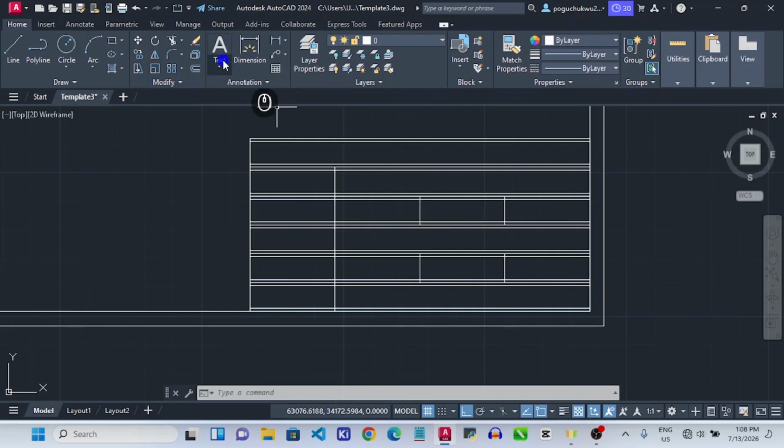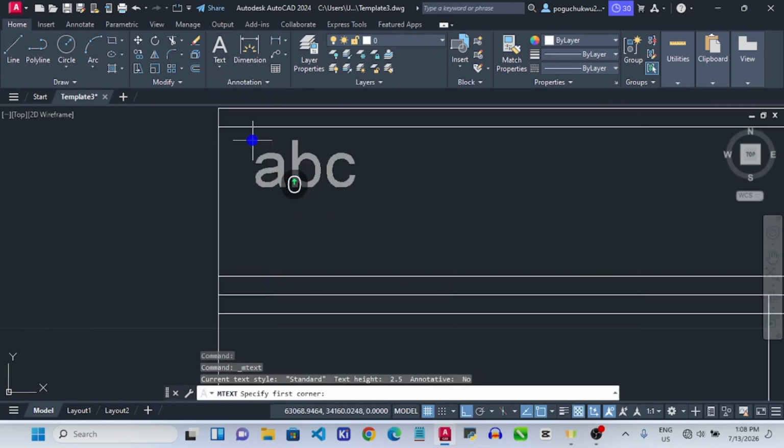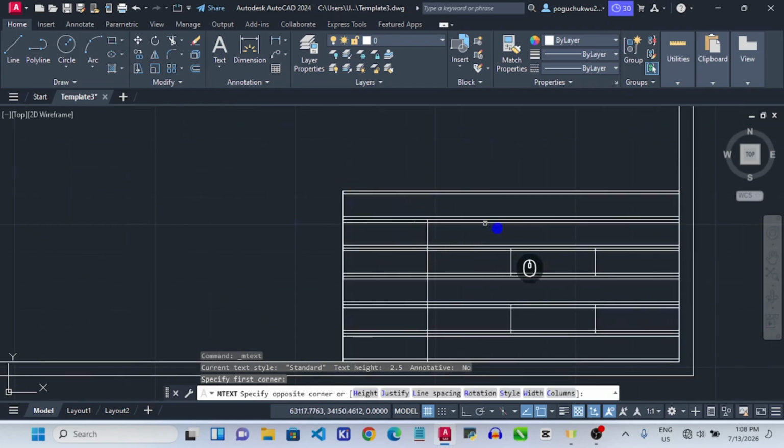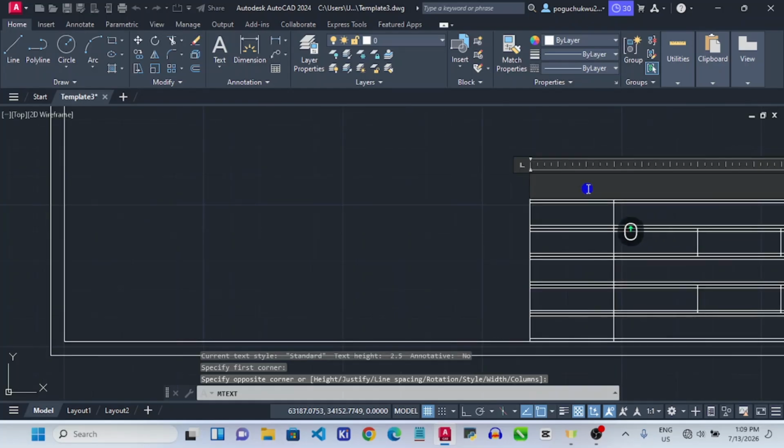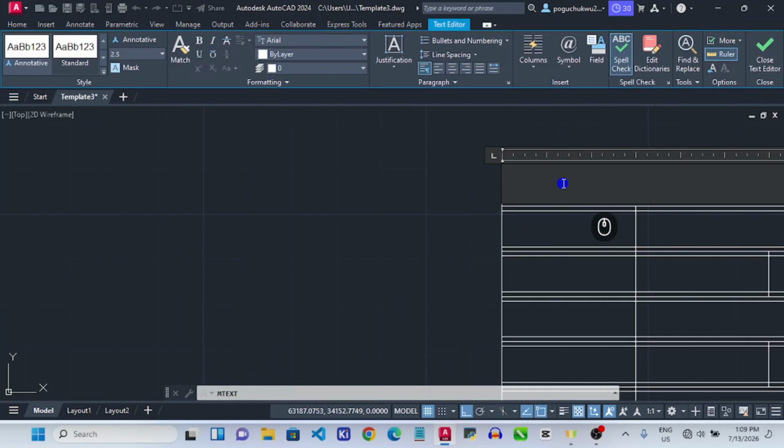That's very easy, actually. Click on this, click on these. This is multi-line text. Then click on these points. We're in the text, we can use the text settings. Just enter, then you see a text, right? So put in your institution name or college name, whichever.